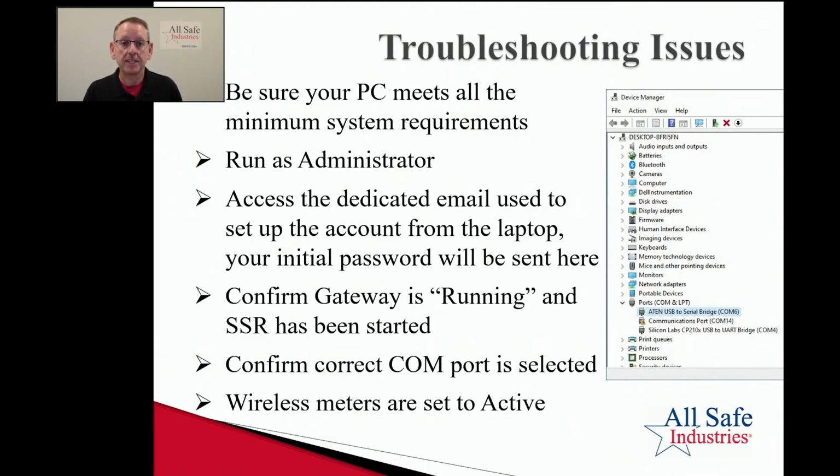Finally, you want to make sure that the correct COM port has been assigned when you're in the Safety Suite Responder program. If you're not familiar, you just type Device Manager in the white block down in Windows. When Device Manager comes up, which you see a screenshot of here on this PowerPoint, you'll scroll down to Ports, and you want to select the port that has that magic A10 cable, the silver cable that converts the 9-pin that you get with your RAELink 3 over to USB. And if you need the driver for that cable, we have that loaded down in the description.